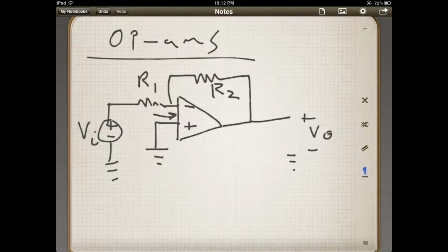It's darn small, because they design these op amps in such a way that they have what's called high input impedance. So basically the input has a very, very high resistance to it. It usually draws anywhere from microamps to nanoamps to maybe even picoamps, depending on the precision and the type of your op amp. So that's a good thing to note.